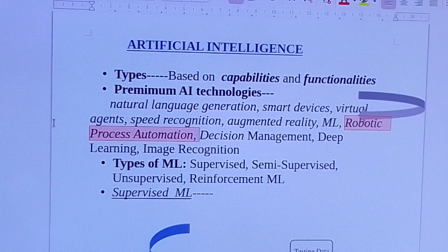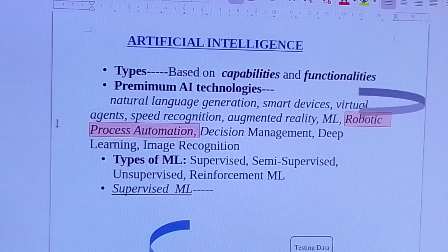Usually, there are two basic kinds of sensors for searching, recognizing, grasping, and placing objects. They are tactile and non-tactile. Tactile sensors are contact sensors that have to be in contact with the object to get signals to measure the necessary quantities, while non-tactile sensors are contactless sensors that sense the signals remotely, but only within the required range of distance from the object. When the tactile sensors make physical contact with the object, an electrical analog or digital signal is generated and sent to the robot controller.